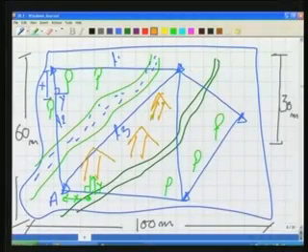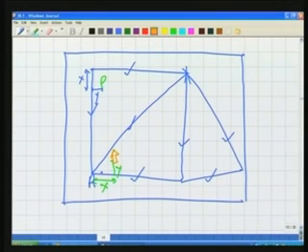Rather, we mapped our area first in a big way. We measured these distances very accurately, the L1, L2, L3, L4, L5, all these, and then we plotted them here. We brought the skeleton of the ground here on our map. So we worked first on the whole, the skeleton of the area. We are not bothered at that stage about the features. But in the second stage, working from whole to part, we make use of the control network, these triangulation figures, and then we start plotting each and every detail.